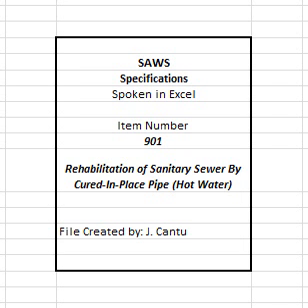Contractor shall also submit to owner at least 5 recent references of the CIPP installer, indicating successful installation of proposed hot water CIPP on projects of similar size and scope. Installer's project manager must have a minimum of 3 years of CIPP installation experience and must be on site during the installation of the CIPP products. 2. Installer equipment requirements. A. Installer shall only use hot water equipment that has been certified and approved for use by the CIPP product manufacturer.